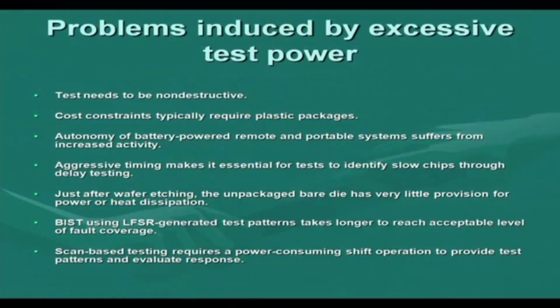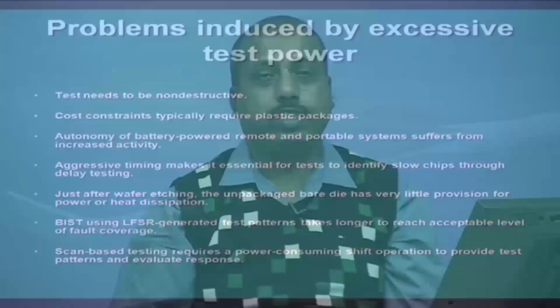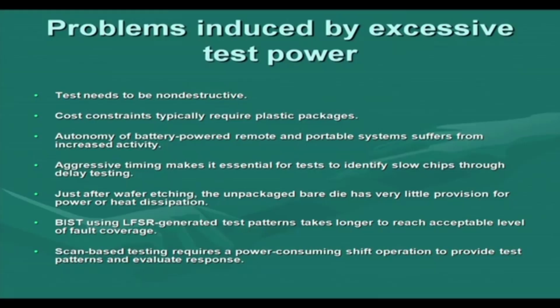Problems that get induced by excessive test power are the following. First of all, the test needs to be non-destructive. So, when we are testing a chip, if the power consumption of the chip exceeds its power budget, maybe the chip will be permanently damaged. So, this has to be avoided. If the excessive test power is high, then there is a possibility that the chip will get destructed.